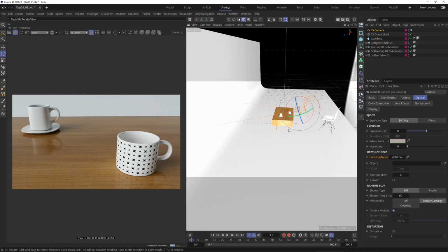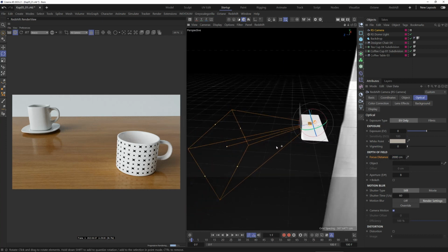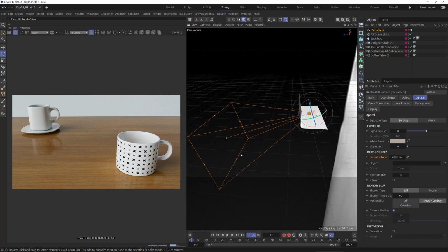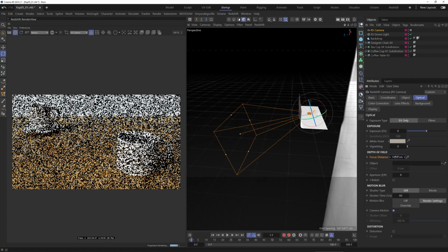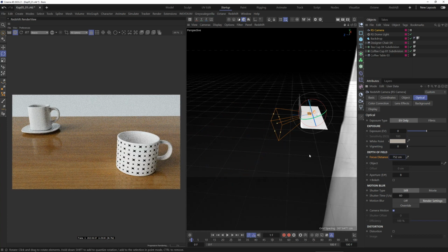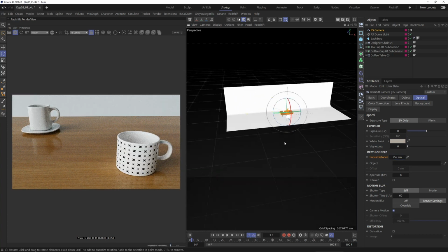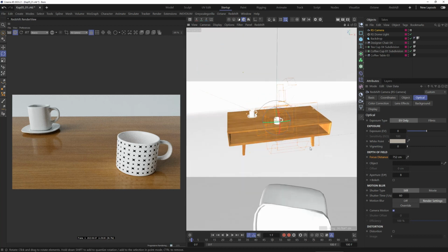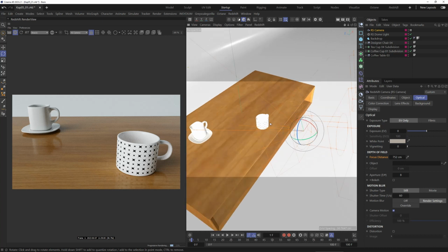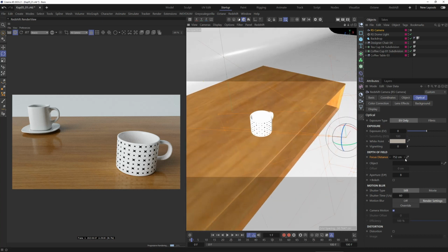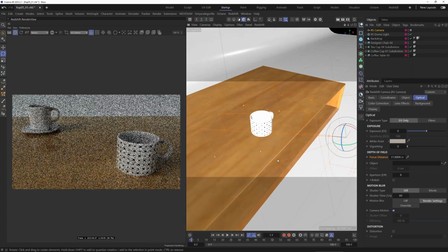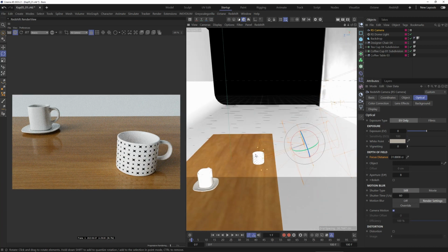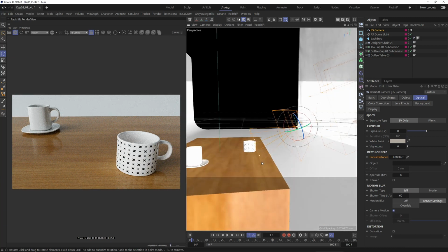which is set to 2000 cm by default. Moving away from that, we see the focus point, the focus distance. I can enter values directly or select an object with the eyedropper. I'm now approaching the scene. To put the focus on the cup, I click on the eyedropper. And then on the cup itself, the square automatically adjusts to the cup.